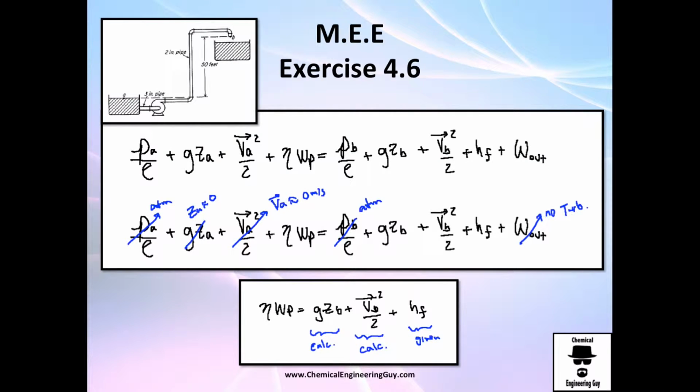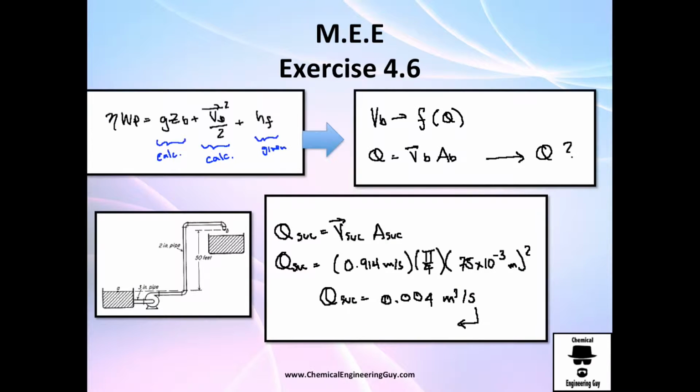Yeah, perfect. And wait for it. Okay, we were here. So even though we don't know the volumetric flow, we can calculate it from here. We know the velocity in the suction, which is 3 feet per second, or in SI units is 0.914 meters per second. The area is essentially pi divided by 4 times diameter to the second power. The diameter is 3 inches or...